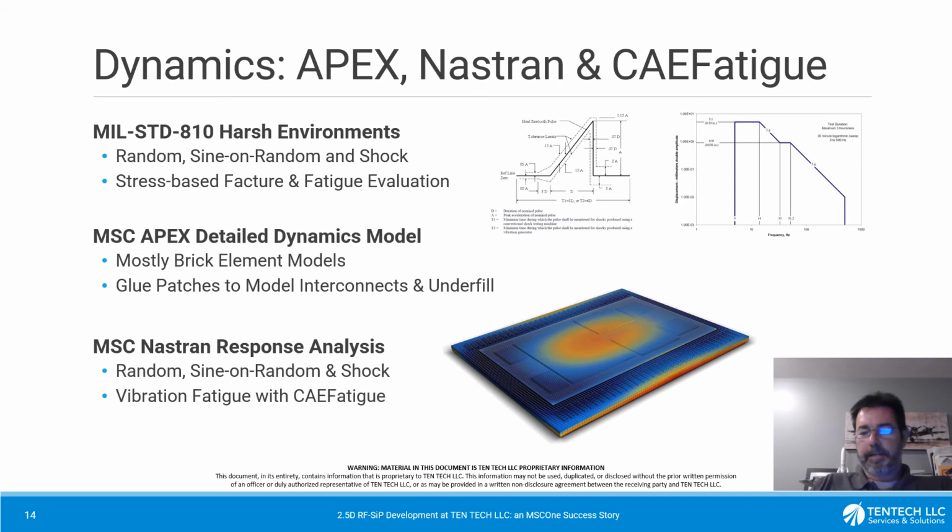We see some dies that we didn't expect to have problems, and it turns out because of the vibration environment or shock environment, the dies are too close to each other and start hitting each other. So now we have issues and we need to redesign. We catch this early on with our dynamics models.